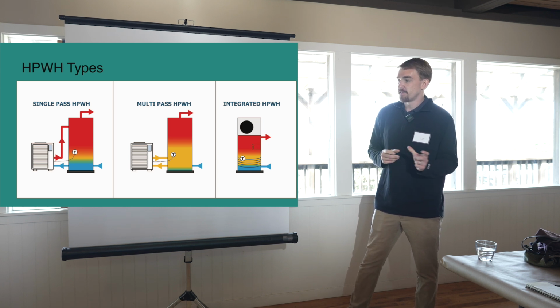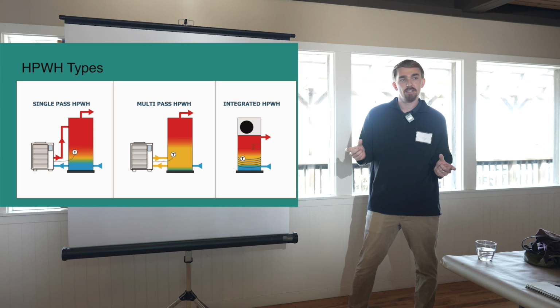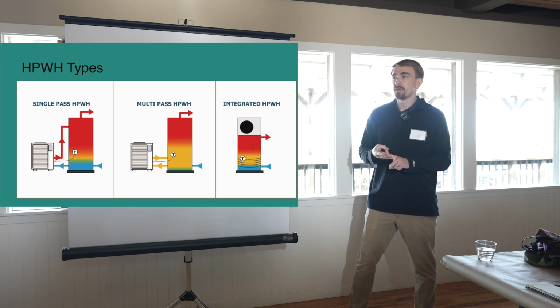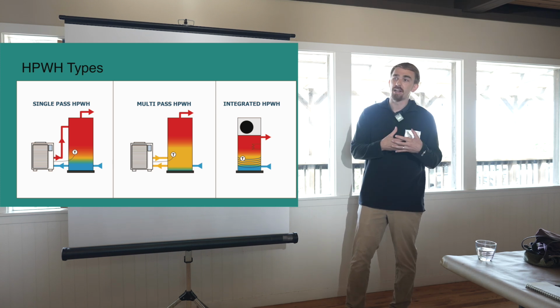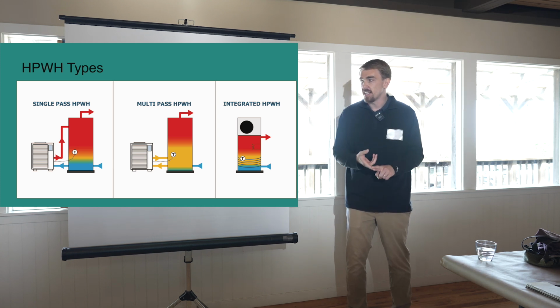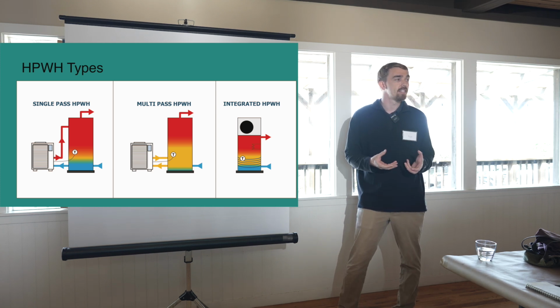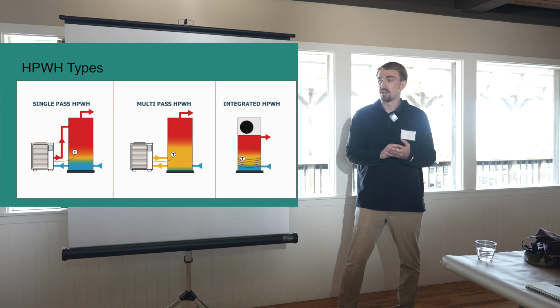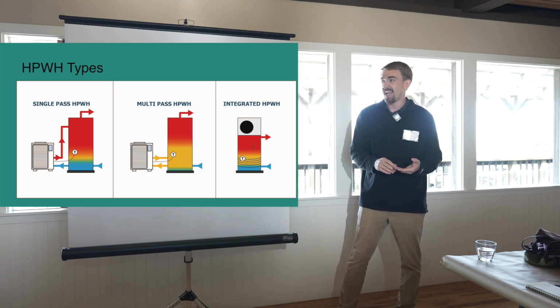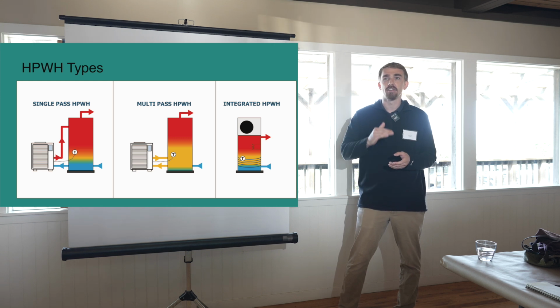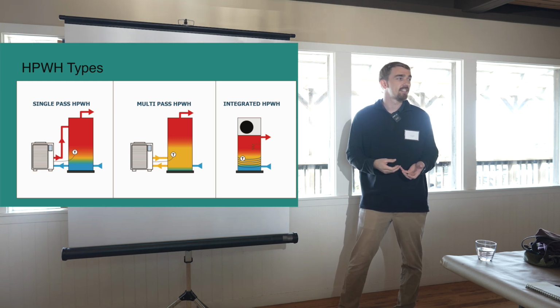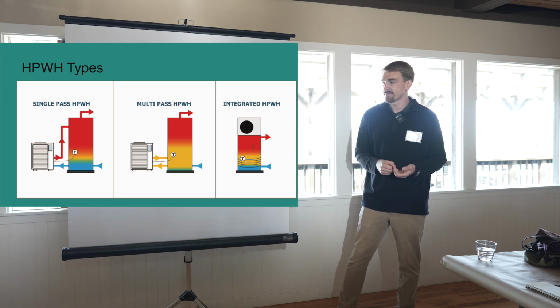So we have two main form factors, but there's 3 components in these systems that are really crucial. The first is the heat pump itself. It's pulling heat from the air, putting it in the water. The second is the storage that's paired with this heat pump, because these heat pumps like really consistent conditions, and they're not very high recovery, so they need this storage to handle those high peak draws if everyone decides to take a shower at the same time.